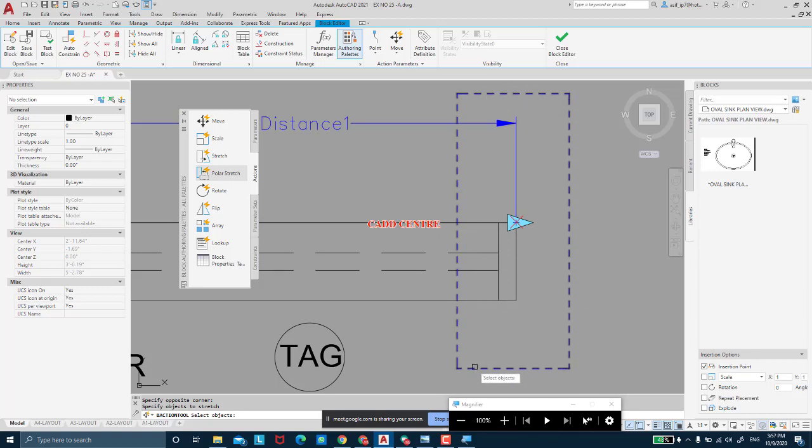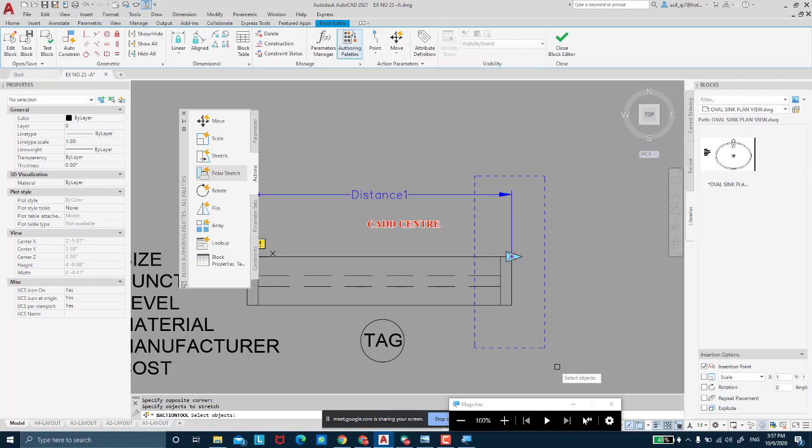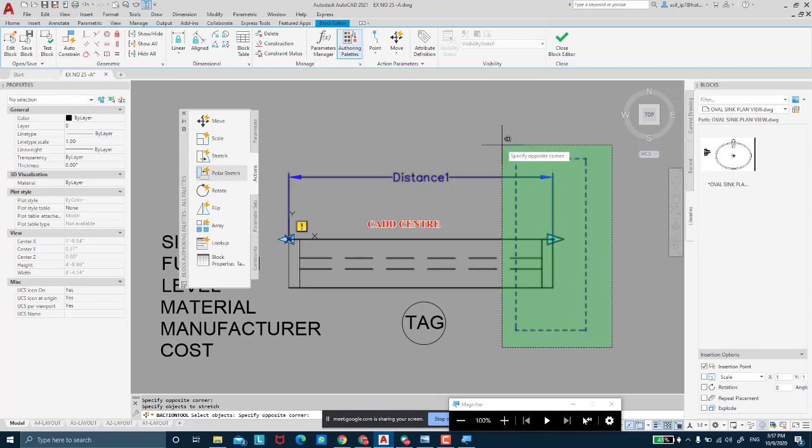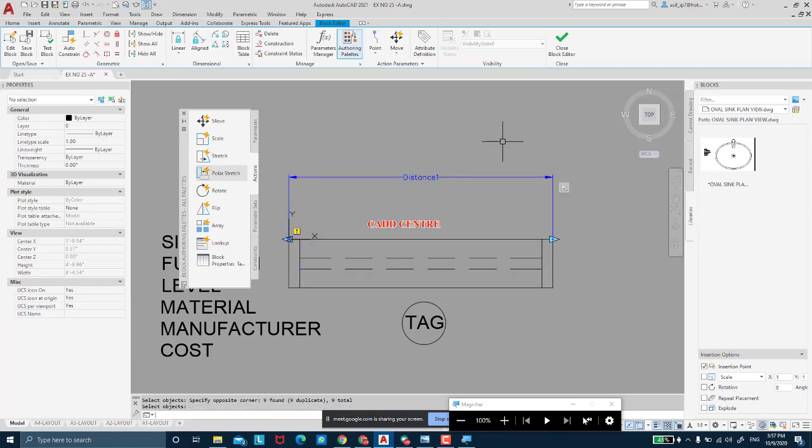Okay, once this frame is there, now we're going to cross select the object. We're going to take the green selection as a cross select, and we'll select this much region. This includes the corner end points of the lines and some part of that dashed rectangle also. So this much is cross selected. Okay, and I'm going to press enter to confirm the selections and everything. Enter, done. You can see stretch modify applied, it will be written there as stretched.